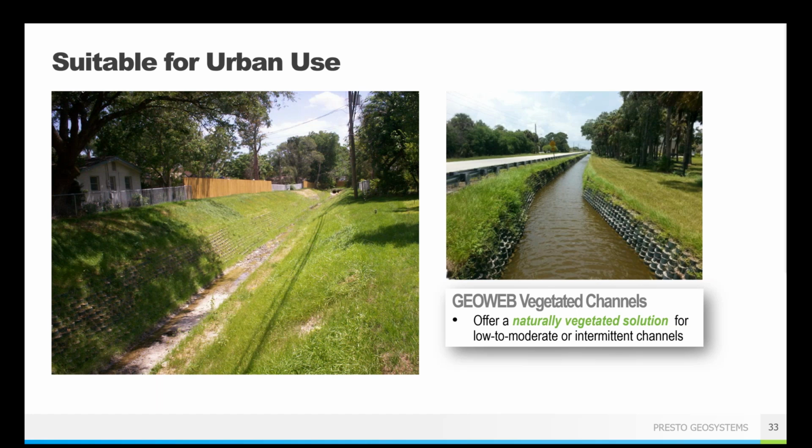If you don't have a lot of footprint to be able to do a nice shallow channel that's maybe 20 feet wide, do a retaining wall where you have significantly steeper slopes, so you have a steep channel to be able to support all of the water and still hold itself in place, but now you've got maybe a 5 foot wide channel. So lots of options there as well.